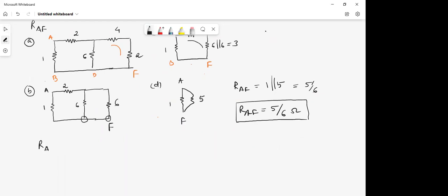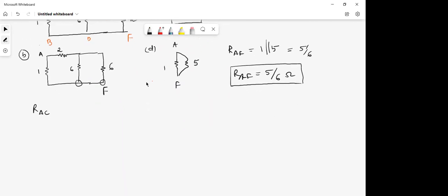Now take resistance between A and C. So listen, now we'll develop the diagram in such a way that only these 2 points are surviving. And now you can increase the speed. Since in the previous sum we saw that B, D and F, all of them are shorted, we can bring them together. We don't need to even redraw them. We don't need to even name them. Now everyone knows that 4 and 2 are in series.